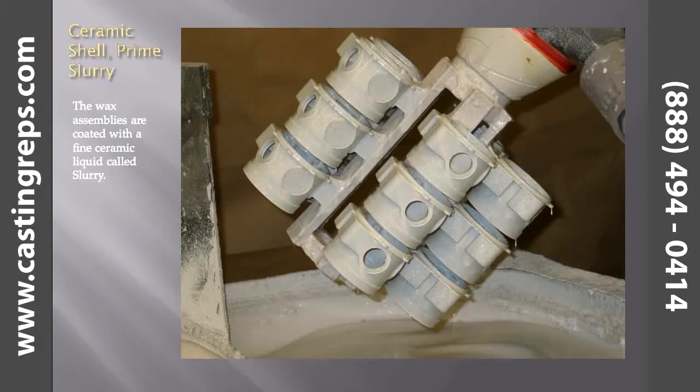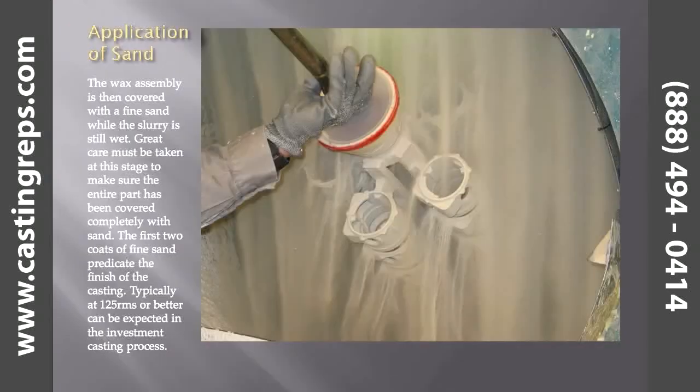Ceramic shell, prime slurry. The wax assemblies are coated with a fine ceramic liquid called slurry. Application of sand. The wax assembly is then covered with a fine sand while the slurry is still wet. Great care must be taken at this stage to make sure the entire part has been covered completely with sand.